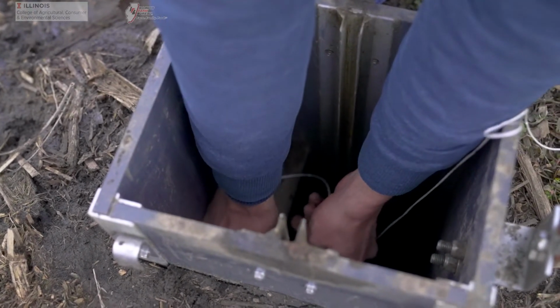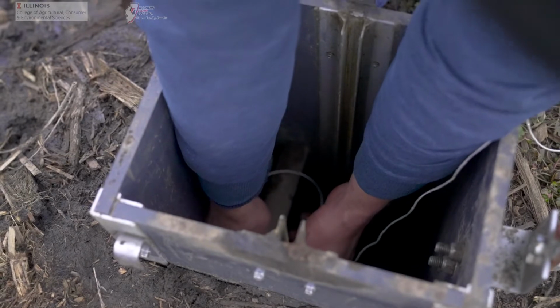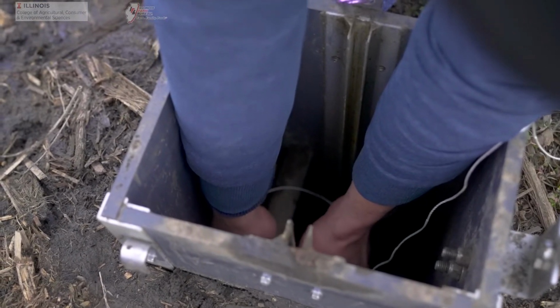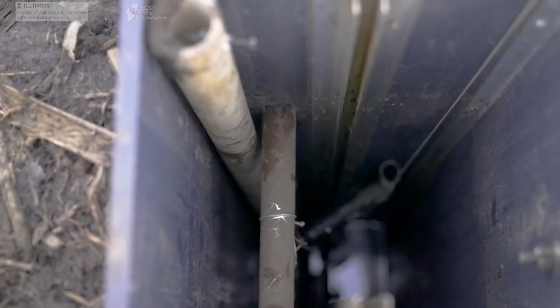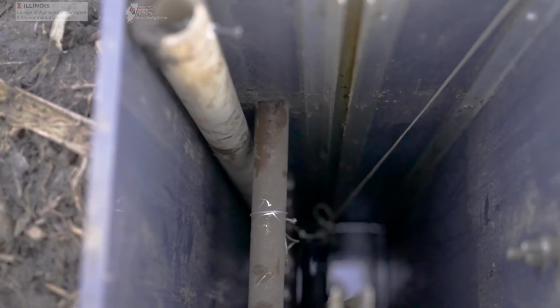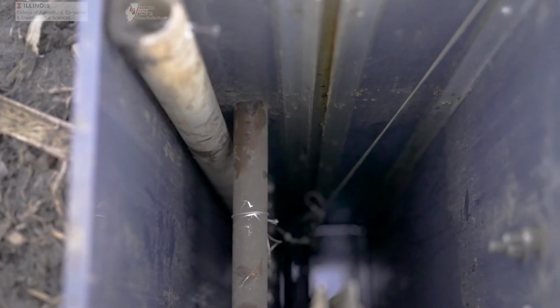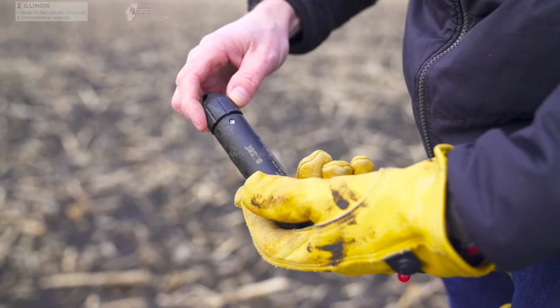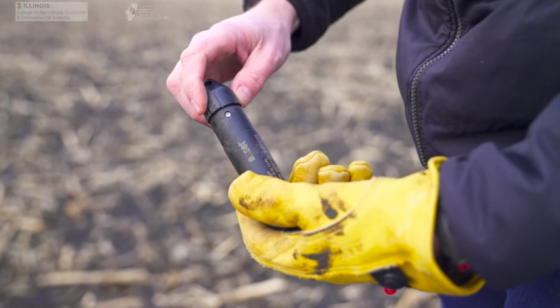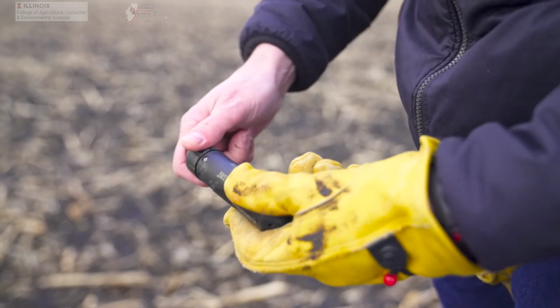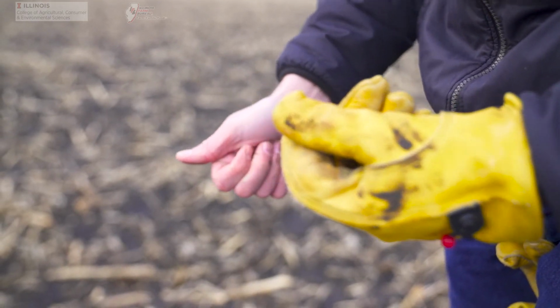The way we record barometric pressure is by hanging a third sensor in the air inside one of the control structures. Secure both ends of the sensor to the top stabilizing bar, leaving enough slack in the line to be able to download the sensor when needed. The sensors can be slippery and are very difficult to retrieve from the bottom of the structure or tile pipe if dropped. Secure them well.